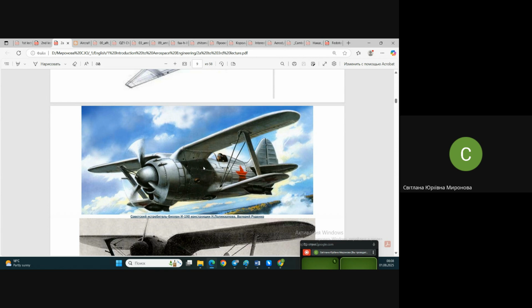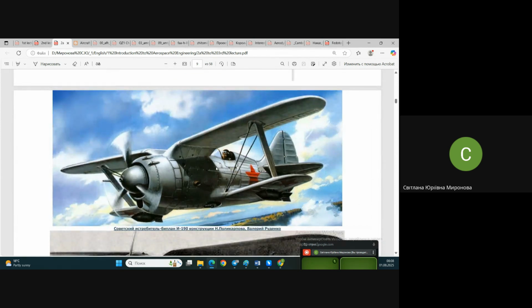And this demand for more compact size results in needing to use to the maximum all the inner volumes, all the inner places of the airplane. It's not possible to place the wing like this at this place. Why? The wing is not joined to the skin. The longitudinal elements of the wing, these spars, compulsorily go through the fuselage in this place.